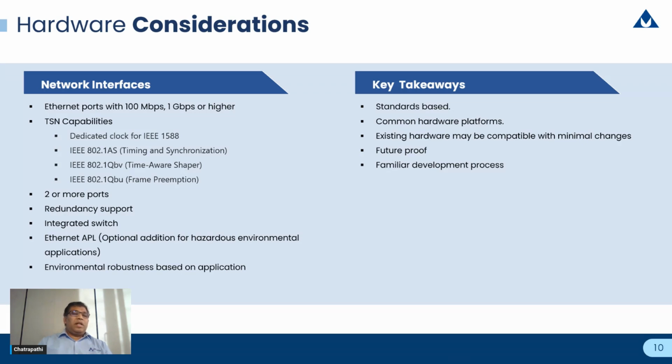So having a dedicated clock for IEEE 1588 integrated as part of the MAC, and then having the timing and synchronization capabilities and time-aware shaper, as well as frame preemption capabilities can be leveraged when you use OPC FX implementation on top of it.